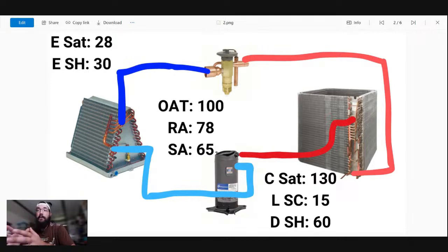Because the low airflow, sorry, the light scattered me for a second. It's just not going to work. Okay, that's fine, I'm just going to be a little dark. With low airflow, I would expect low superheat. So my evaporator superheat is far too high to think that it could be some kind of oil logging issue or something along those lines. So I would remove that from the equation because of that.